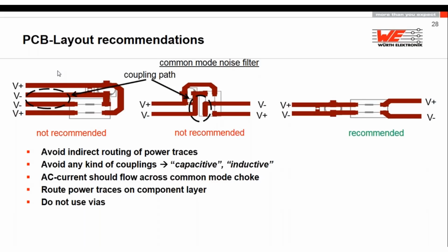So his homework was now to go home, solder this, and make a PCB solution of these in-air soldered components. But we told him, please don't modify too much on the PCB. Just push a little bit, make a little space to fit these additional three components on the PCB and make them as close as possible to the connector. Well, he pushed away the PCB and he put in this common mode choke and these two capacitors. And finally, he went back to the EMC lab with his new redesign number one, and he failed again.